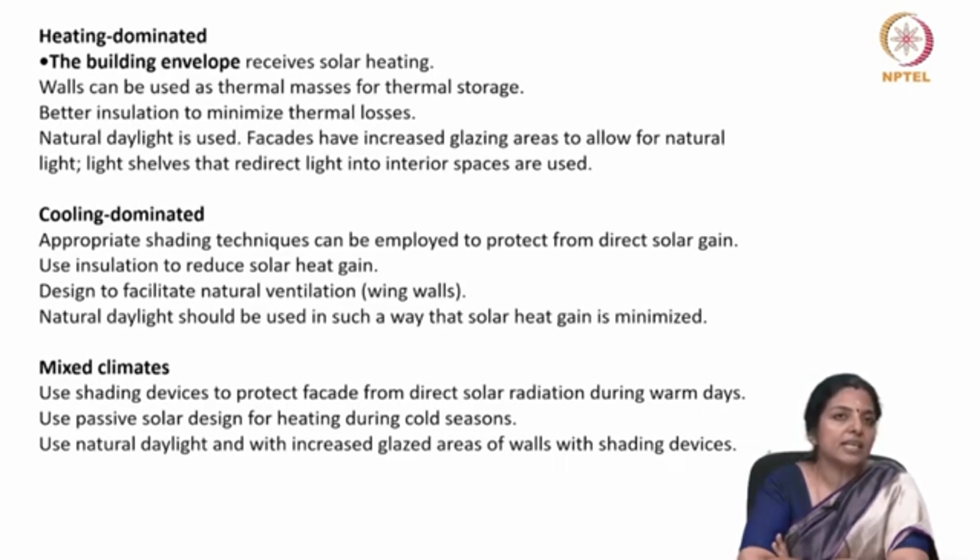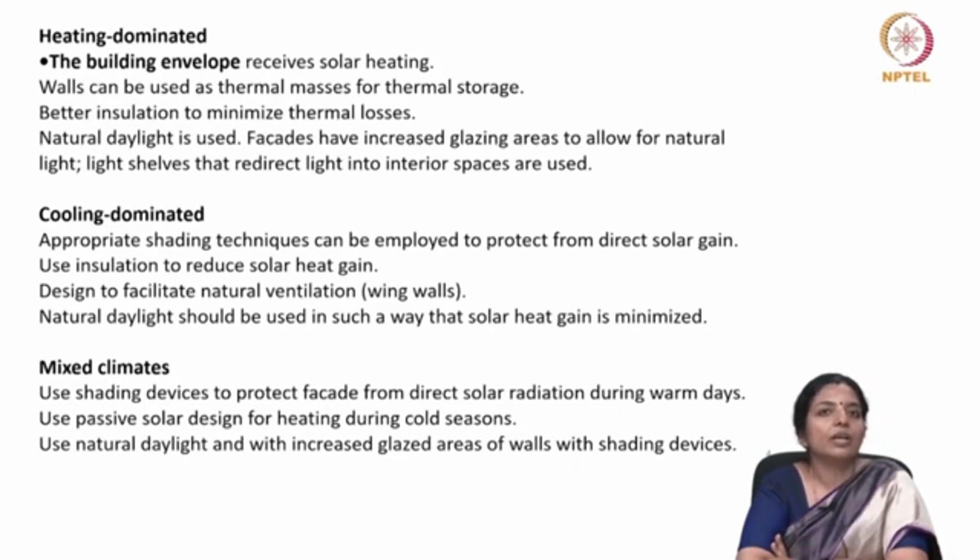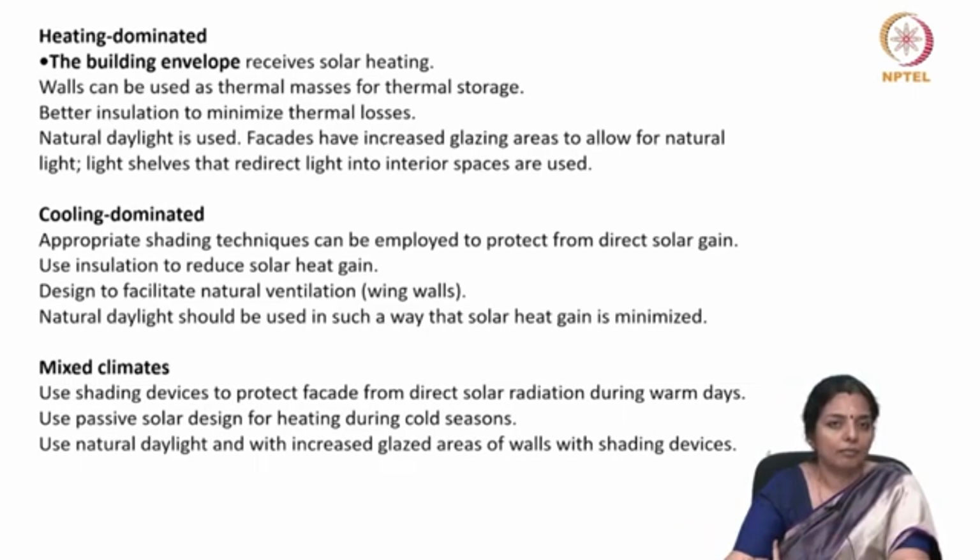Whereas in mixed climate, we must have shading devices to protect the facade from direct solar radiation during warm days, while using passive solar design for heat during cold seasons. Using natural daylight with increased wall areas and with shading devices will benefit most.